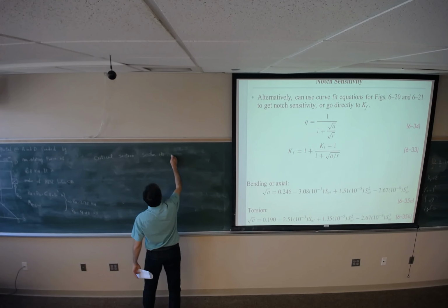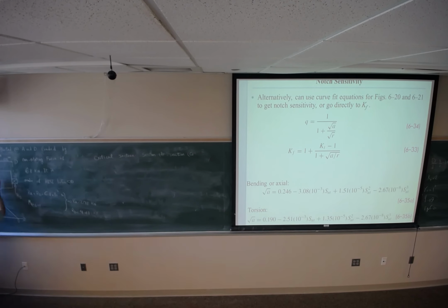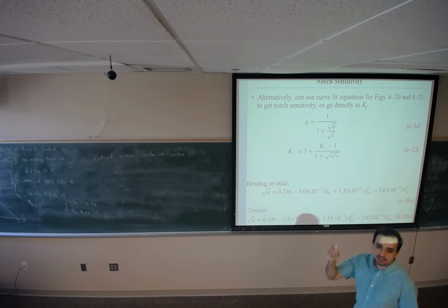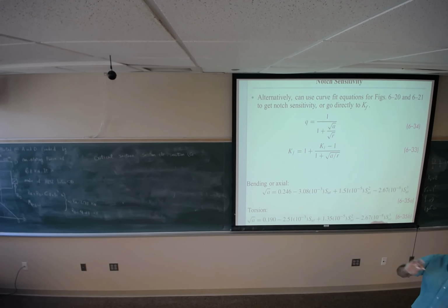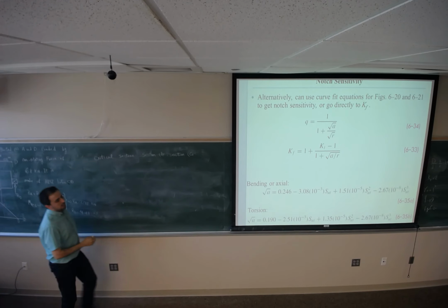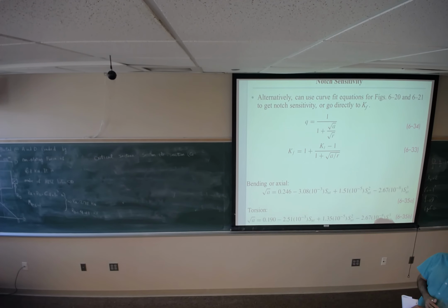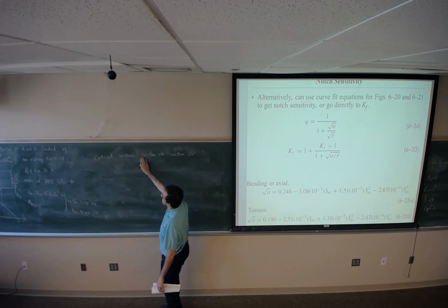Why not section B? Because section B also is going to see the stress concentration, and it's a smaller component, but we don't know how much the bending moment would be to compare B and C. Another section that you should study is section E, because section E is going to see the largest bending moment, and you don't know how much stress is going to develop at section E compared to the stress developed at sections B and C.